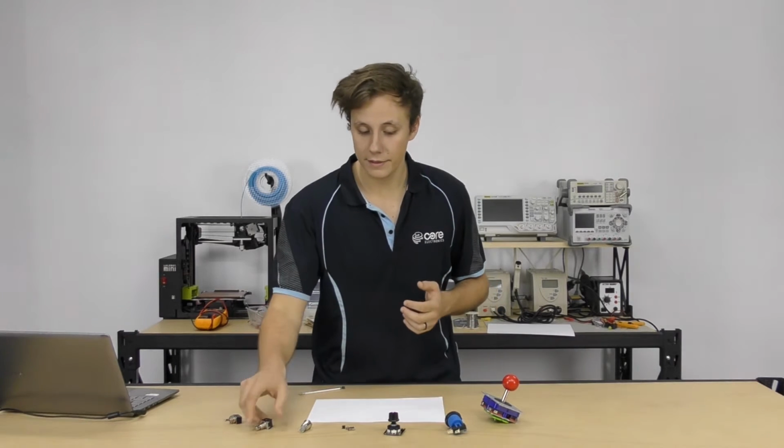Latching means that the switch will hold its position mechanically when it is turned or pushed or toggled into a state. Take this switch for example: you can hear a definitive click and then another click, and that's toggling between two states and it's latching in between, like the clicky point on your pen. That latches, it doesn't have to be held there constantly when you want to write.